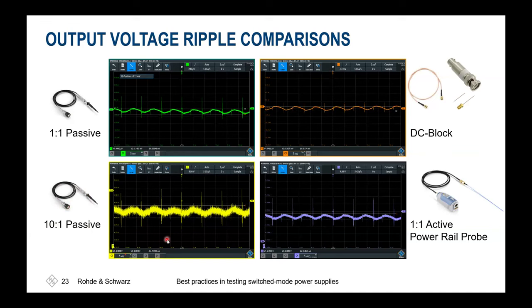And as the oscilloscope recognizes this 10x1 divider ratio, it's automatically multiplying every sampled voltage point internally with a factor of 10. So also the base noise of the instrument is magnified by a factor of 10. And if you look at today's oscilloscopes, typically you'll find in smaller vertical scales an input noise of about 1 millivolt peak to peak quite easily. And if you remember the previous table, you shall qualify a ripple of up to 10 millivolt peak to peak. So 1 millivolt of noise multiplied with a factor of 10 would immediately cause you some issue because you would have then already 10 millivolts on screen, and then every additional peak would cause you a violation of your target.